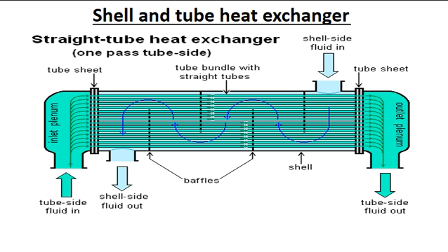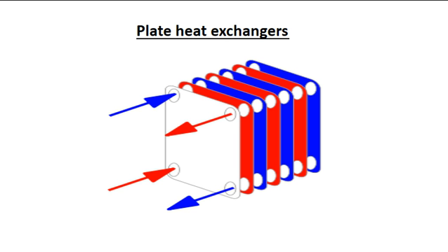Next to it is the plate heat exchanger. These are composed of many thin, slightly separated plates that have very large surface areas and small fluid flow passages for heat transfer. Advances in gasket and brazing technology have made the plate type heat exchanger increasingly practical. In HVAC applications, large heat exchangers of this type are called plate and frame.